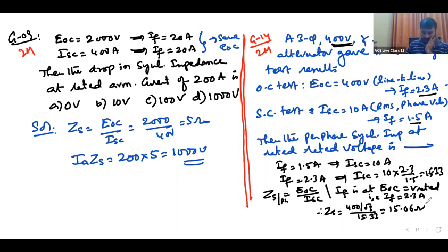Right? Now, lastly, the only thing is you have to find for which field current. Both must be for the same field current. He is asking for rated voltage, means rated voltage at 2.3. So calculate short circuit current also for 2.3. Then take the ratio. Last question.